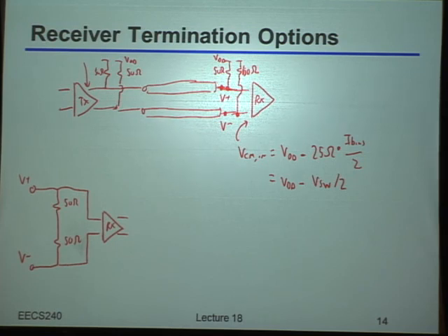Yeah, basically the 1/2 is gone. In other words, this is lower because now from a common mode standpoint, those 50 ohm resistors don't show up. Right? They're not pulling you up towards VDD. If you remember, this is kind of like how we drew our common mode sensor circuits. We just said if we put two resistors and a bridge across it, it wouldn't change the common mode. It would just measure what it was in the center point.